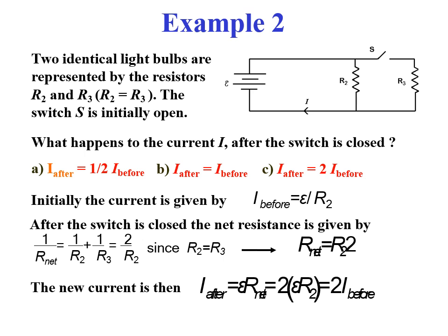Now, let's make an example whereby we have a 20 volt supply, and resistor 2 and resistor 3 equal to 10 ohms. At first you will have resistor 2, which is equal to 10 ohms, supplied by 20 volts. 20 divided by 10 will be equal to 2 amperes. That's the initial current.